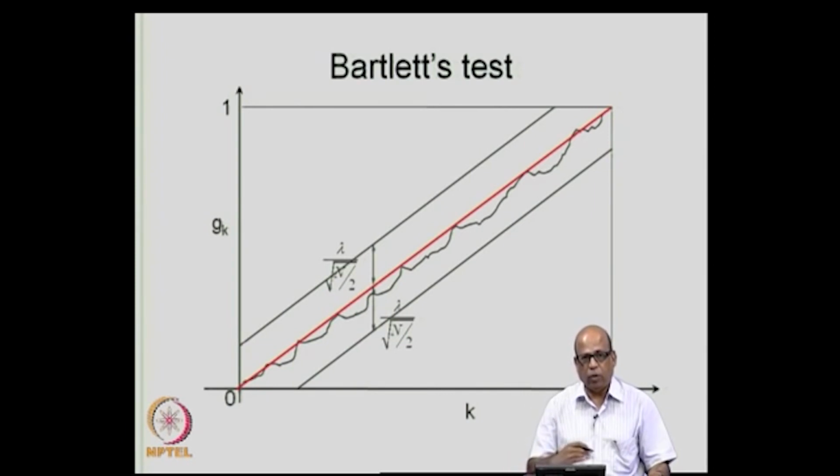With respect to lag k, you calculate the G_k values and plot this, and immediately the significance comes up. Whereas in the first test that we had, we formulated a statistic corresponding to each of the periodicities that we suspect to be significant, and we have to make that particular test for each. Therefore, Bartlett's test is preferred for the test of periodicities.